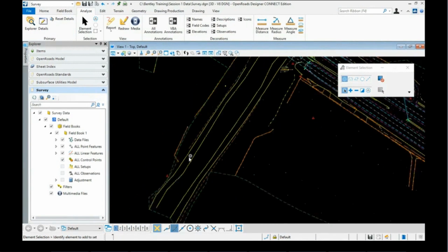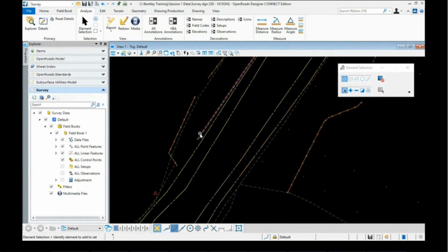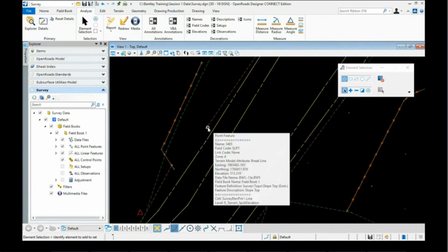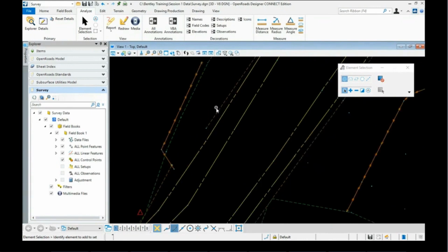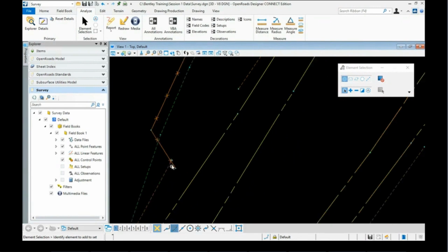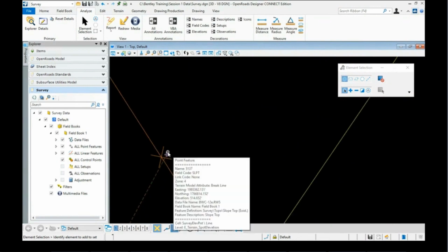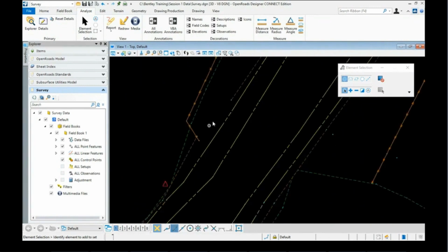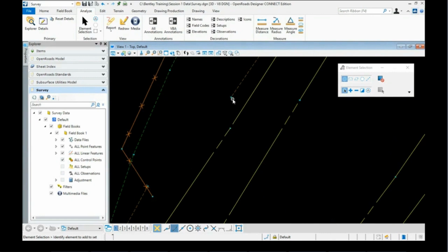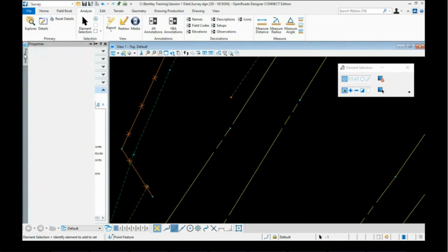And now to clean that up, I want to connect the end of this string to the beginning of our next string. So I'm going to add a control code, a join point code to this string to connect it up with this string, still using the linking code methodology. So I'm just going to write down real quick what number I want to connect it to, 5137. And I'm going to edit my point up here, and that chose the string there.